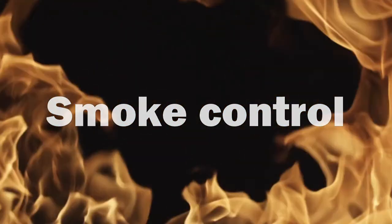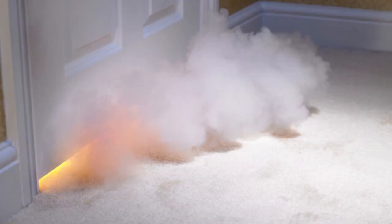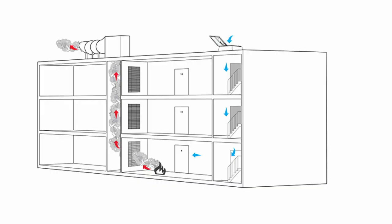Smoke control. The majority of people who die in fires are overcome by the smoke and gases. In larger buildings, there may be some form of automatic smoke ventilation provided. These systems are designed to restrict the spread of fire and smoke, usually by venting the heat and smoke through the roof or via other routes to the outside. Low-level inlet air is essential for this, and all openings for this purpose should not be obstructed.